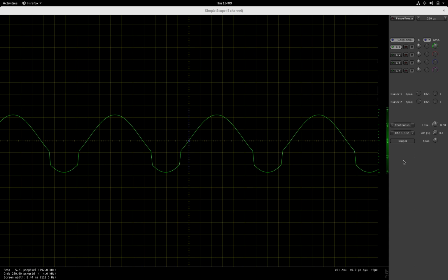So okay, what I will show you now is if I reduce the input amplitude to the fuzz unit, of course if this bias voltage were a constant voltage that was added to the input signal before it is passed through the nonlinear amplifier circuit in the fuzz, then there would be a point where the amplitude of the input signal is no longer large enough to reach this nonlinear region.